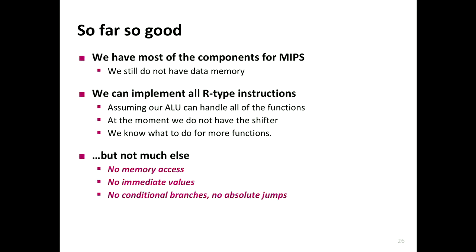For the register file, we had 32 registers, and therefore the addresses were 5-bit. In MIPS, we saw that the data values can be 4 gigabytes, which means 32 bits. And you, of course, have a clock.